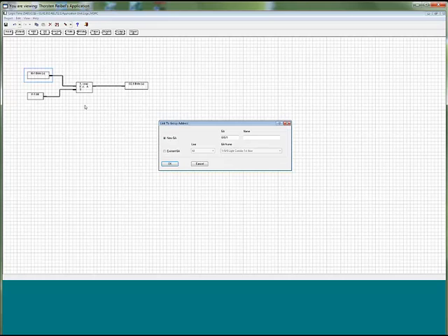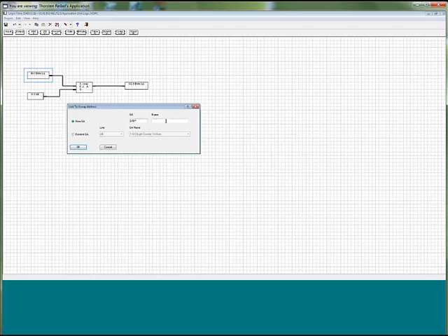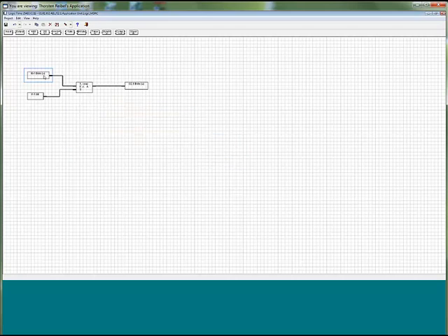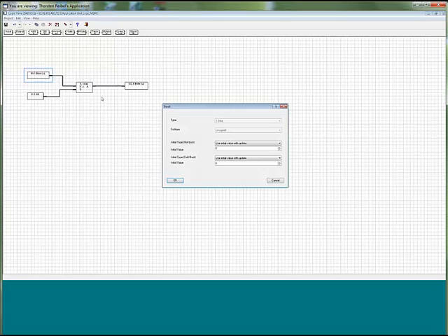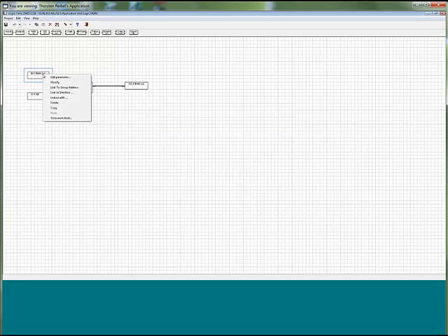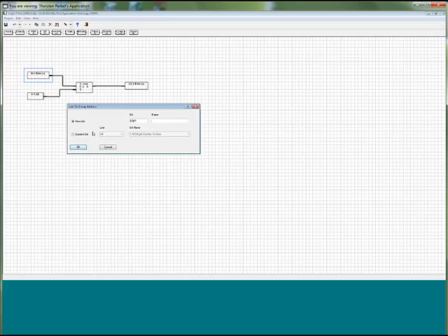Then our group addresses will pop up here. You can create a new group address if you want, or you can use an existing one in all the lines, one which I have not used before. I select here one of my group addresses, like for example my Office 1, click on the button OK. Oh, wrong type. I have to use a one byte, sorry. Edit parameter, sorry. Link group address, link to group address, existing group address, a group address which is not used before. Let me use, for example, this here.